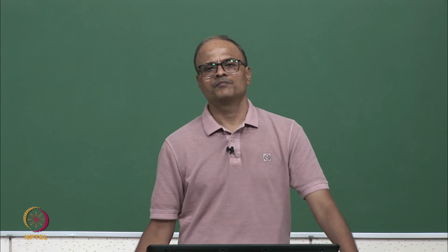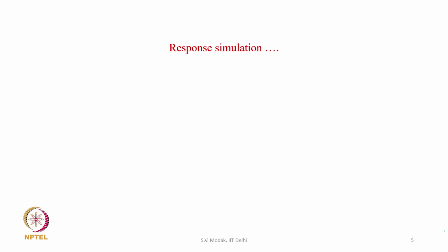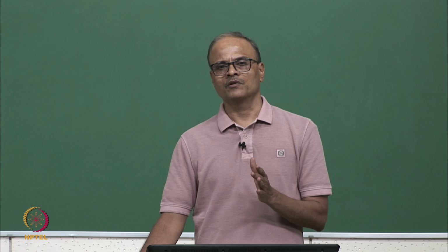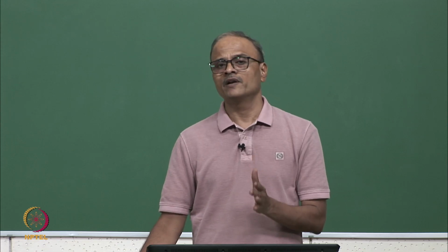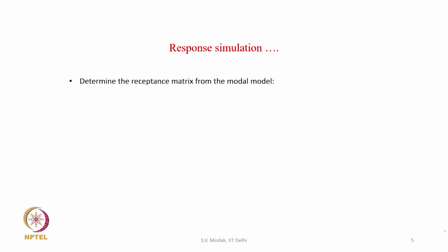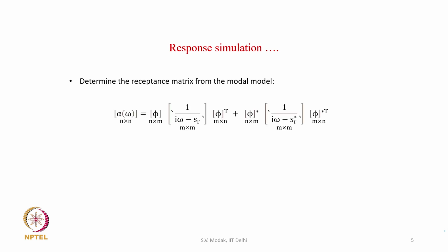So, how to perform response simulation? Once we get the experimental model from the modal test, we can compute the receptance FRF matrix of the system. We have studied earlier the relationship between the receptance FRF matrix and the model. For a multi-degree of freedom system with non-proportional damping, this relationship is given by this expression.